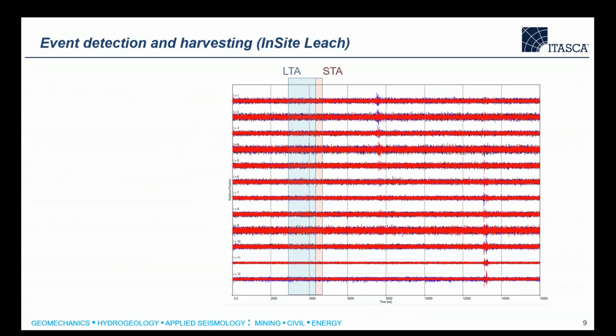And that's what's tricky, as it involves more processes. But basically what it tries to do is detect when our stream meets a certain criteria, normally based on amplitude, that will tell us that there is an arrival. It's an amplitude that is above the normal background noise. So anything that goes above that noise should be a signal.